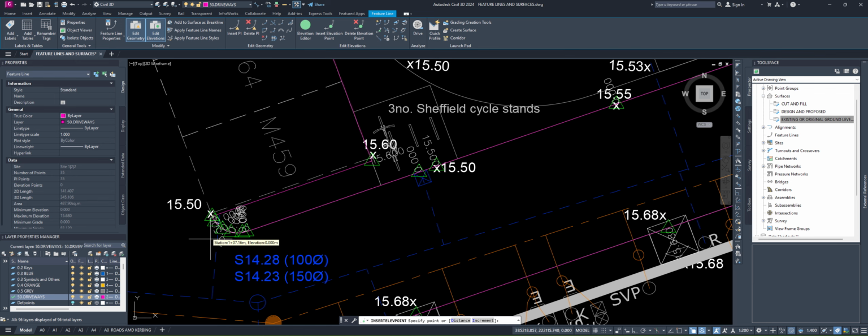All I can do is create a point only along the line without changing the direction of the line. If I want to create a PI point, that is going to allow me to change the direction of the line as well, not only create elevation but change the direction of the line.